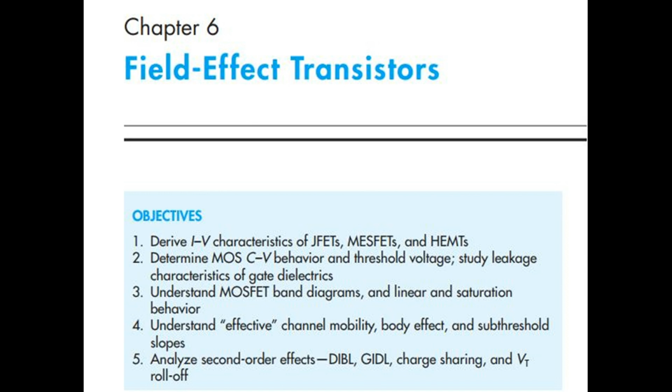2. Determine metal oxide semiconductor current voltage behavior and threshold voltage, study leakage characteristics of gate dielectrics. 3. Understand metal oxide semiconductor field effect transistor band diagrams, and linear and saturation behavior. 4. Understand effective channel mobility, body effect, and subthreshold slopes.